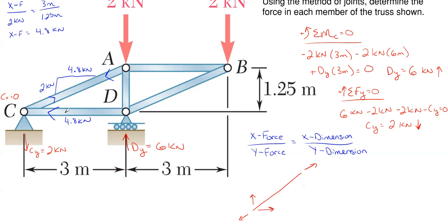And it has to be in tension all the way across if it starts in tension. So looking at CD here, we have an arrow that is pushing on C. Pushing represents compression. So that means it has to be in compression at the opposite end as well. It cannot change from tension to compression until it hits another joint. So we are pushing on C, so we have to be pushing on D.